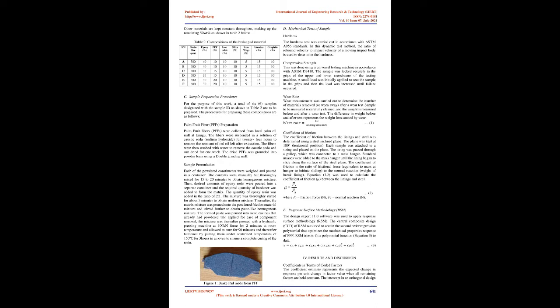Structure and chemical composition of the friction layer generated on the friction surface significantly differs from the bulk. Mechanochemical interaction occurring in the friction process is compared to a non-friction situation where an equivalent apparent temperature and compressive loading, respectively, were applied to the same material. No simple relationship exists between composition of the friction layer and bulk material formulation. Phase stability and kinetics of interactions for friction and equivalent non-friction loading conditions differ significantly.